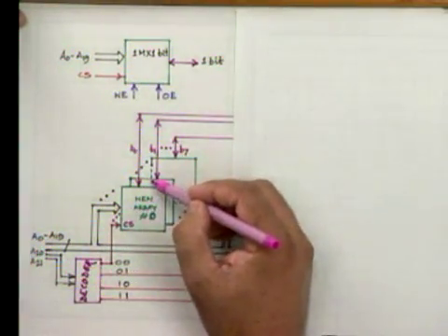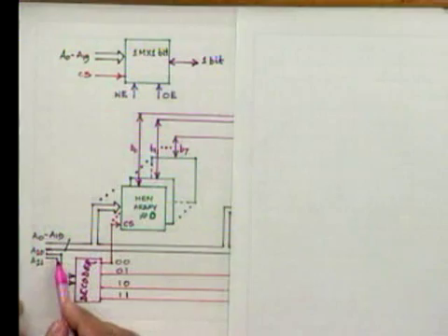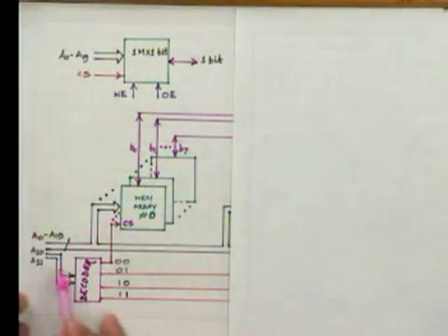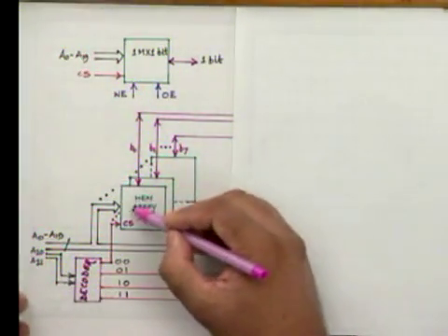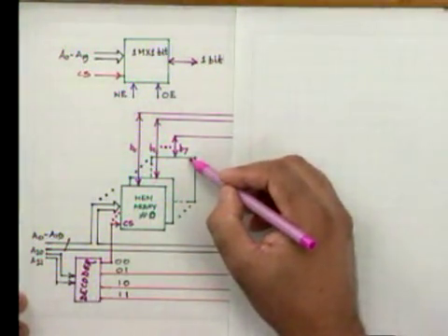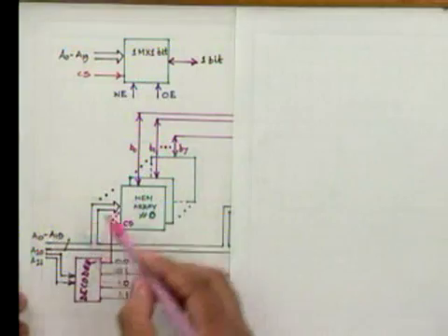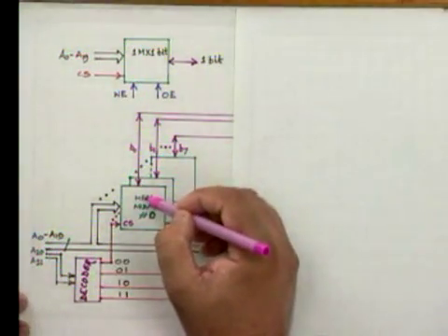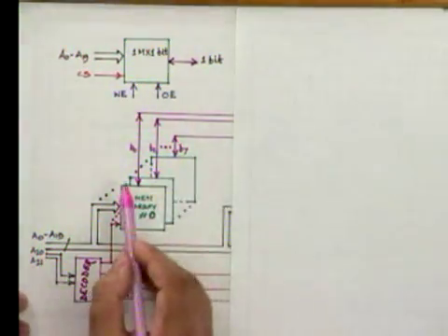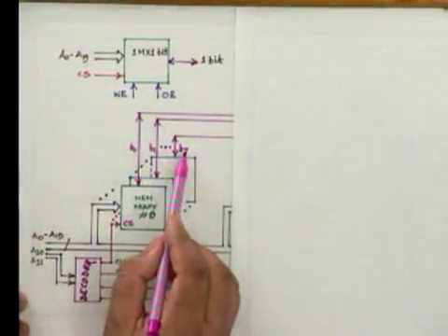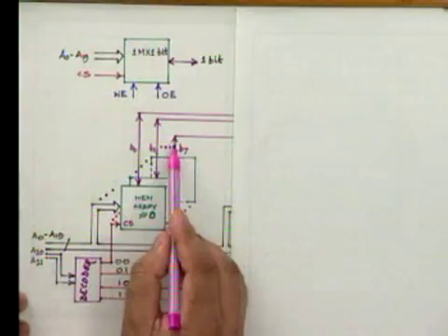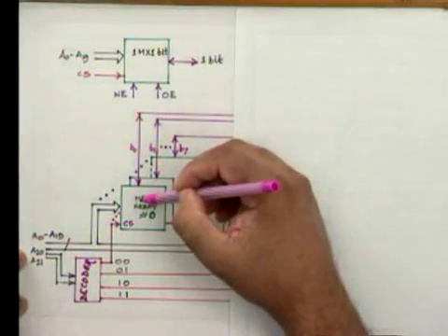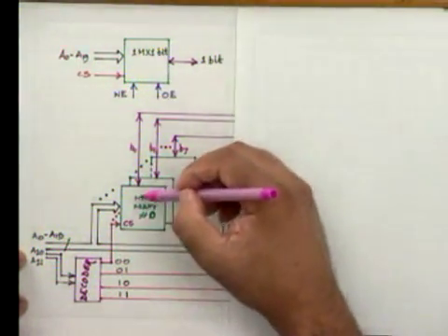This goes here as well as here as well as here, which means for a particular 22-bit address, depending upon A20, A21, if it is 0, 0, then the entire stack here is selected, and depending upon A0 to A19, one cell and the corresponding cell of each of these planes, that means each of these chips, is selected, therefore making the B0, B1 to B7 lines output, in the case of a read, the content of the corresponding cells in each of these chips, right?